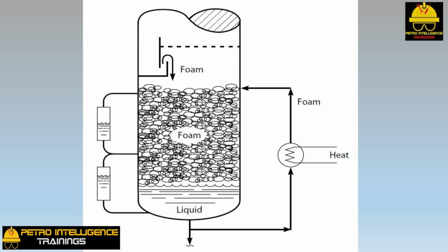In a circulating reboiler, the reboiler effluent flows up the riser as a froth. Of course, the flow from the bottom of the tower is going to be a clear liquid. Foam cannot be pumped. But there will always be some ratio of foam to clear liquid in the bottom of the tower, and we have no method of determining this ratio or even the density of the foam. Well, if we do not know the average specific gravity of the foamy liquid in the bottom of a tower, how can we find the level of foam in the tower? The unfortunate answer is that, short of using radiation techniques, we cannot.